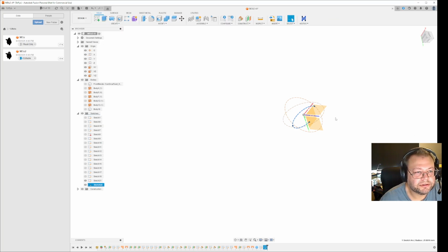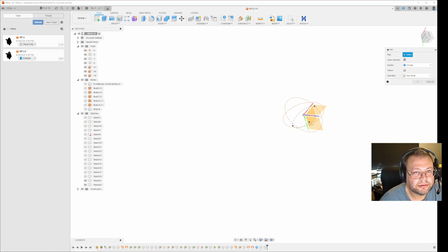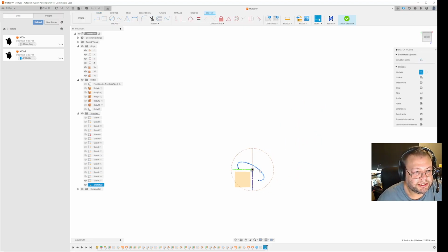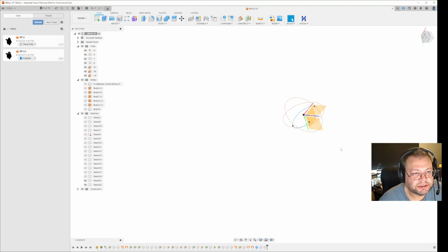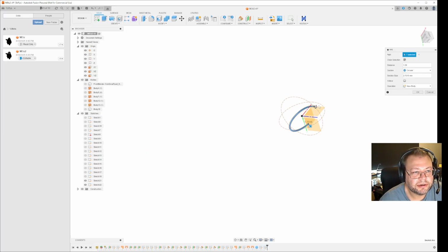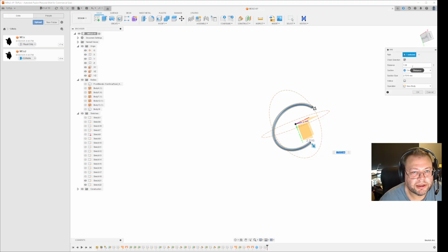I actually have to go out of the sketch, so I can select it, and I can select a pipe. But a path needs to be solid, of course. There, like that. Finish. Select that. Create pipe. Make it section size 5.